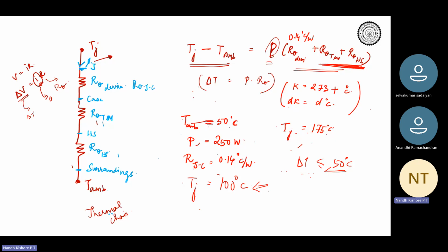Okay. So if you're operating an electric vehicle, there will be acceleration, there will be steady state operation. You will operate at 20 kilometers per hour, you will operate at 100 kilometers per hour. So for the worst case, at 100 kilometers per hour, you will have maximum torque and maximum current will be drawn. That is where your converter is operating at the worst case.